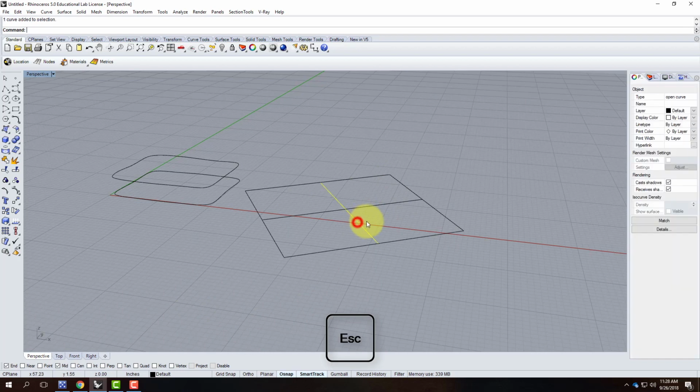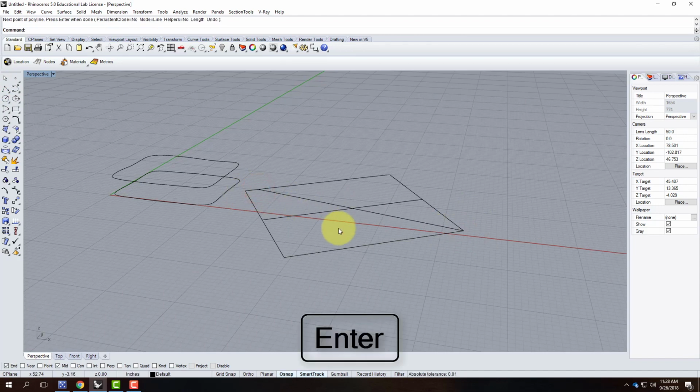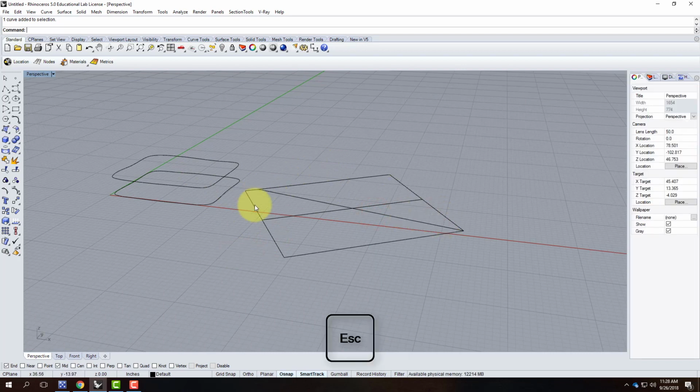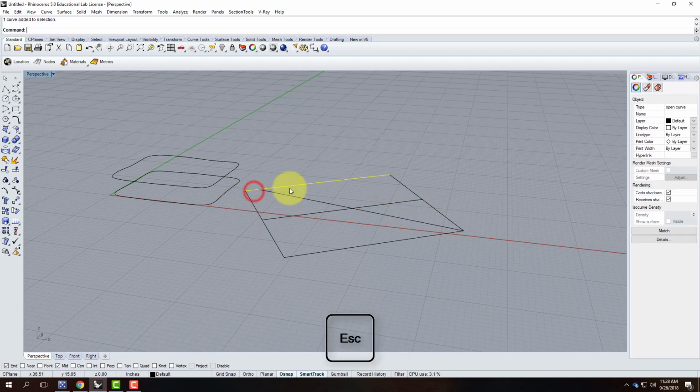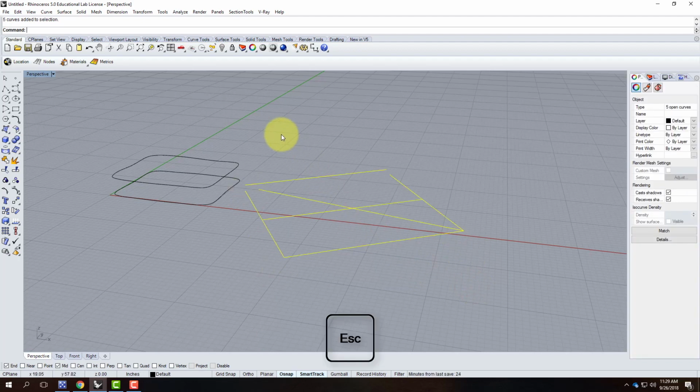It would also still be acceptable to have a line that did that went across this, because it's still generally going in the same direction as these lines. Where it gets unhappy is if you have this condition, where it's not completely enclosed, you have an open-ended thing, or if you have a line where these 2 are joined, and it can't determine which direction this line is. In some cases, you can do these L's, but you have to be a little bit more careful when you do it. So let me show you some examples so that this starts to make sense.